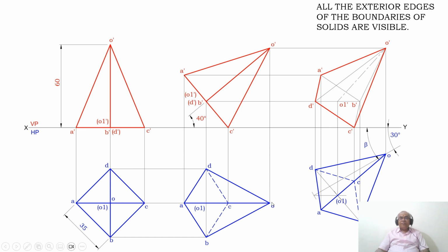So I need to find out the apparent inclination. From the projections of lines on the apparent inclination, we are going to get the apparent length. On true inclination, you are going to get the true length. Apply the concept. Consider any point with reference to the horizontal. Using the protractor, you measure an angle of 30 degrees downwards, then mark that point, join that 30 degree line from this point and extend it. This is going to be the true inclination line.